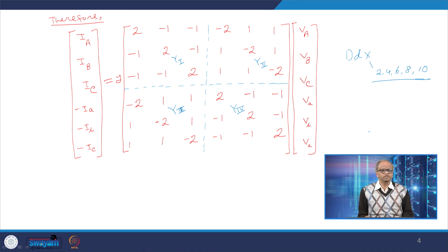We have shown several examples of how to model different types of three-phase transformers. Of course, we have not considered any unusual types of winding. We have considered the most common types of winding, that is Y and D, at both sides in any combination. But we have also considered how to take their group into account.